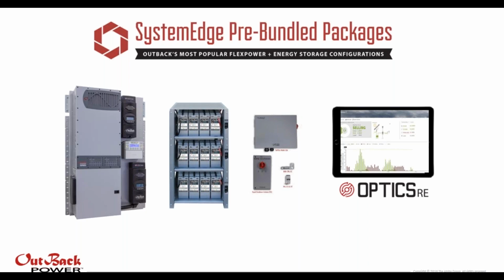They also include the batteries and any associated rack for those batteries. Again, in the picture you see there, we've got some NanoCarbon batteries, the 200 NCs, and they're in one of the IBR3 pre-wired battery racks. Here, just the nature of batteries, you are going to have to put those in, but the switching and the cabling is already integrated into the rack, so all you really have to do is connect the little battery bus bars together and put the covers on the rack, and you're good to go there.